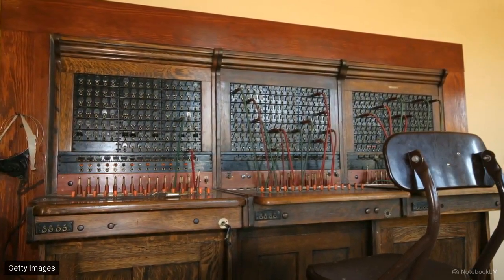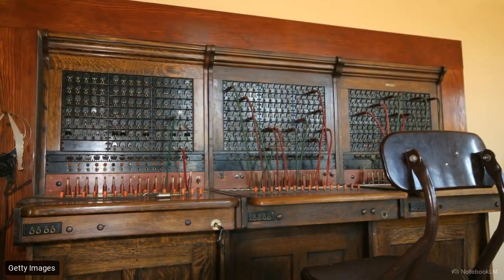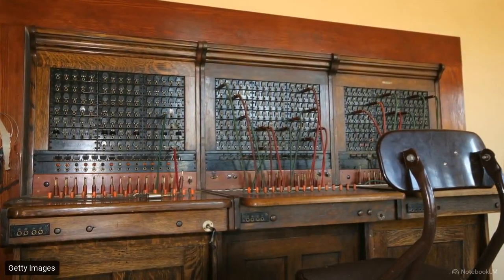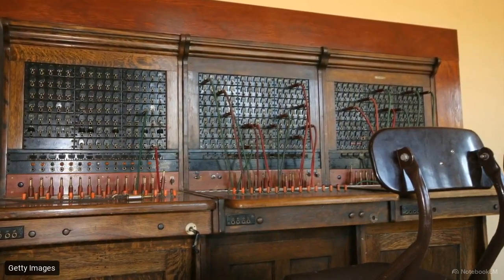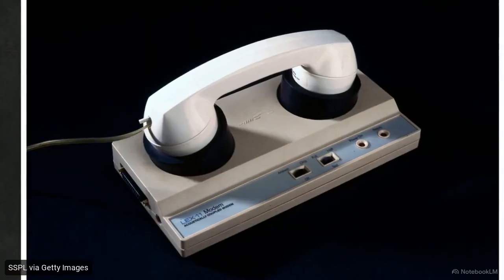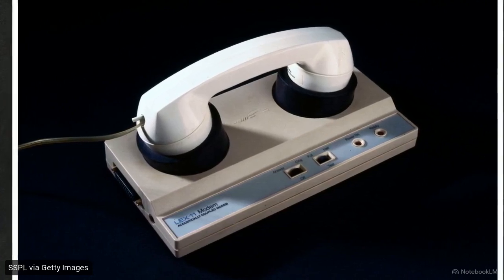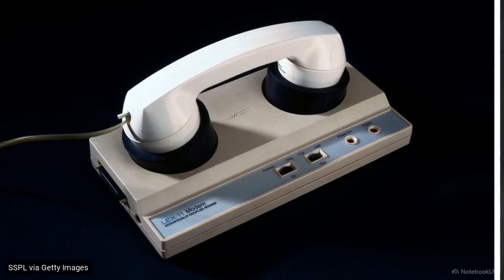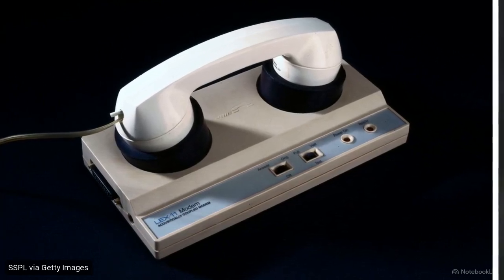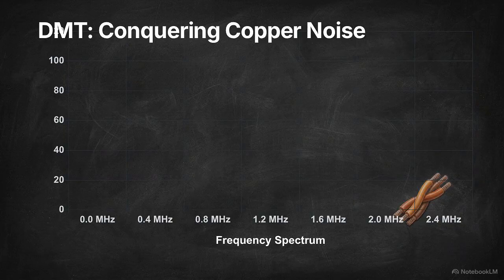At the telephone company's central office, hardware filters deliberately clamped the frequency of every twisted pair down to a mere 4 kilohertz to prevent lines from interfering with each other. Early dial-up modems had to operate entirely inside that narrow, band-limited analog voice channel, squeezing maximum spectral efficiency out of frequencies that were originally meant for human speech. This chart maps the frequency spectrum of early broadband.